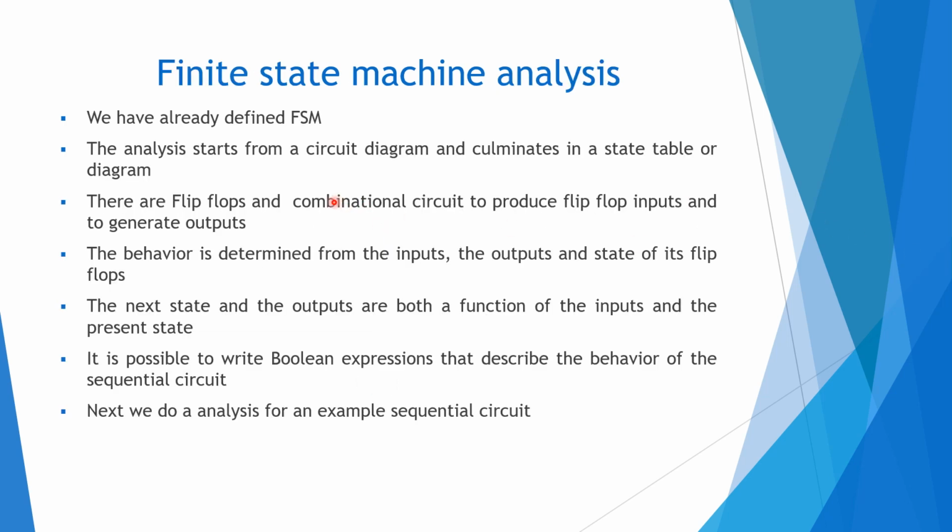So we'll be analyzing one finite state machine in order to understand what is an FSM, or what is a synchronous sequential circuit. We have already defined FSM. It is some inputs and some flip-flops and some outputs, which generates a function of the present state of flip-flops or the inputs, according to the Mealy machine or Moore machine. The analysis starts from a circuit diagram and culminates in a state table or state diagram.